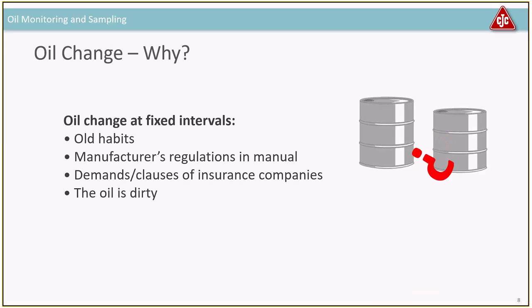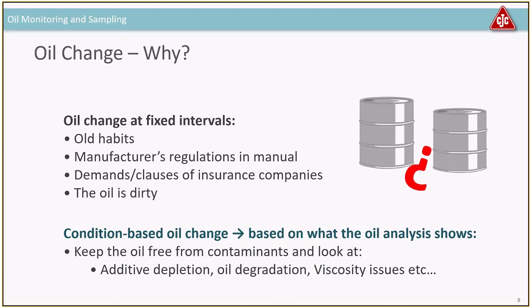But what you should be doing is monitoring the oil and looking at its condition. Based on what the oil analysis says, you can change the oil, but very often you can just keep it clean and in good shape, and then look for the additives, look for oil degradation, viscosity, and so on.